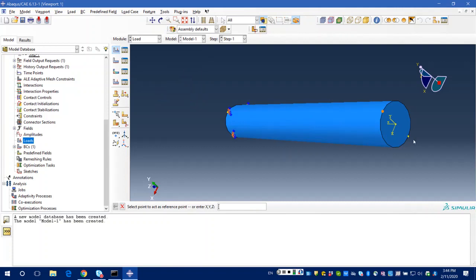These points are highlighted. This means that you can select one of them and define it as the reference point. So I just select this center, okay? Just press once. So here you see RP1. So the reference point is selected. And then after I select it, I just click this X to cancel this procedure.